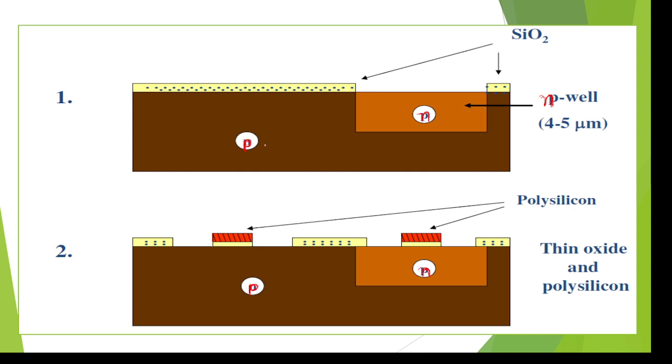Here you can see this. To design the N-well fabrication process, we need to take a P substrate from the silicon substrate. This is a P substrate, which has holes. Oxidation means the total surface is covered with an SiO2 layer. This is common for all, and it gives protection for the surface. Then diffuse the electrons, because it is a holes material, P substrate. By heating this material we are diffusing electrons into the P substrate. So this is the first step.